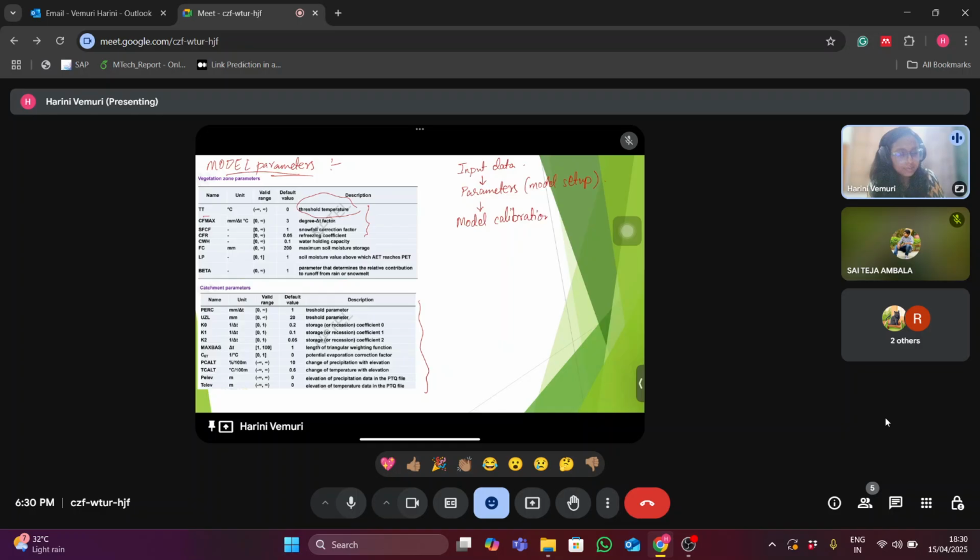So we have discussed what calibration is. Suppose here we are calibrating the model based on runoff. We have observed runoff data, and whatever runoff the model generates is called simulated runoff. We will use some objective function, like minimizing the mean square error or maximizing NSE, such that the error between the observed and simulated runoff is reduced, and accordingly the parameter values will be changed when you are calibrating.